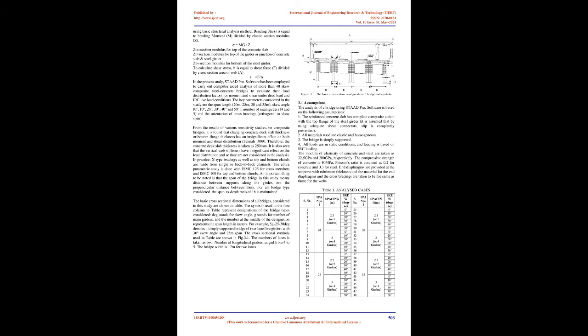Conner and Huo, 2006, studied significant discrepancies in girder distribution factors that have been observed between actual bridge field testing results and AASHTO code predictions. To study the effects of parapets and aspect ratios, 34 two-span continuous bridges with a 0 degree or a 45 degree skew angle and with varied structure parameters are analyzed using the finite element method.